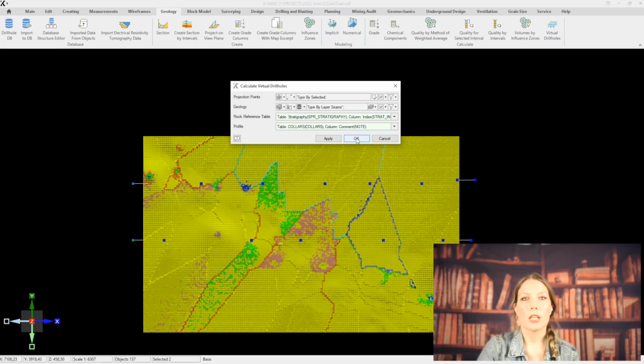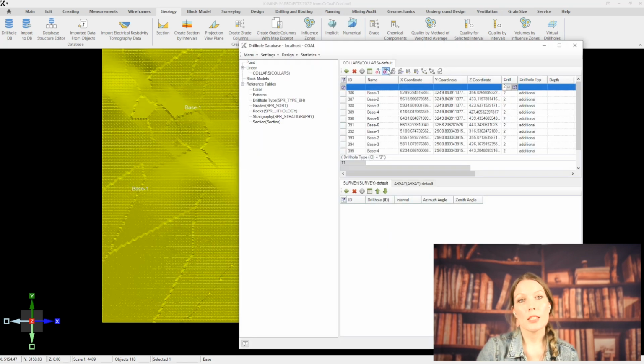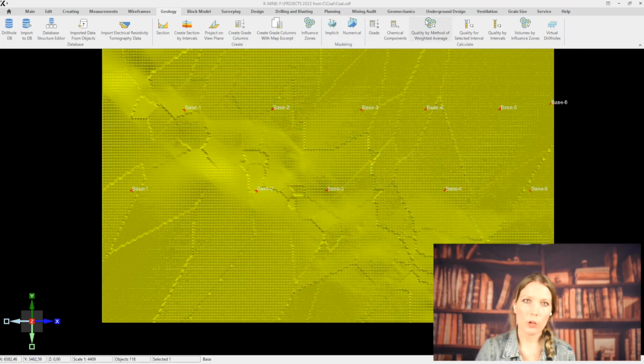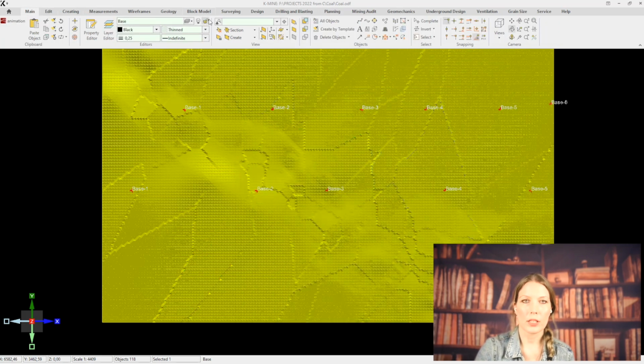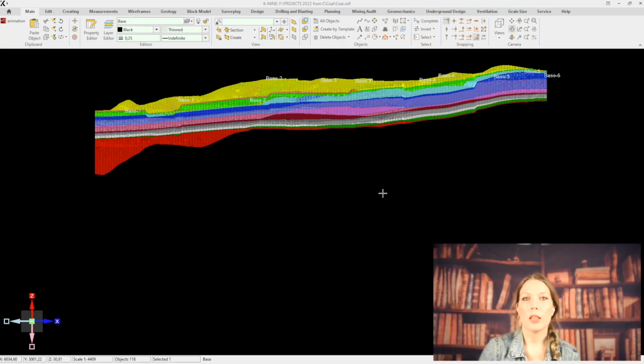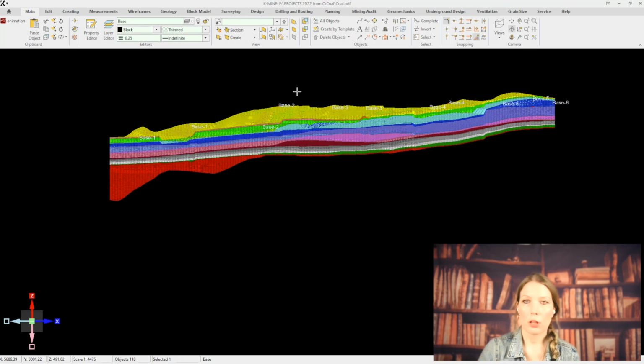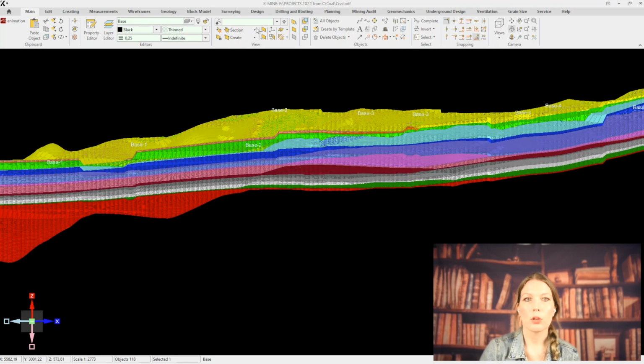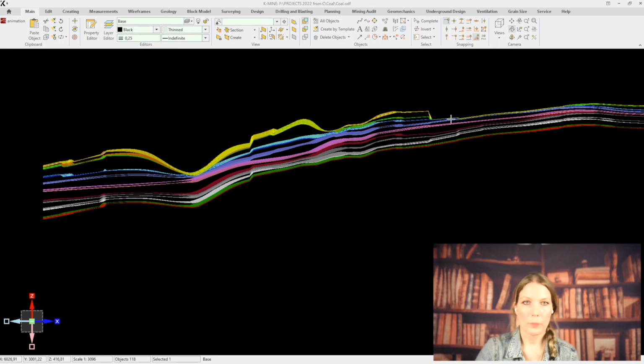First, in the reference table of the database, specify the names of the varieties, like layers or domains, and these names should match the names of the sublayers in the layer editor where the corresponding solids or surfaces are saved. All rock varieties will automatically be added into the assay or the lithology table with thickness calculated and intervals defined from and to.